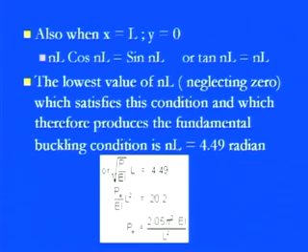And you see here, in the loaded situation at the strut part, where the pin joints are there, the vertical force is being added, and due to that at the fixed end the moment is there. With inclusion of all those conditions, the crippling load is coming out as 2.05 pi square EI over L square. So now you have a clear comparison of the main situations.